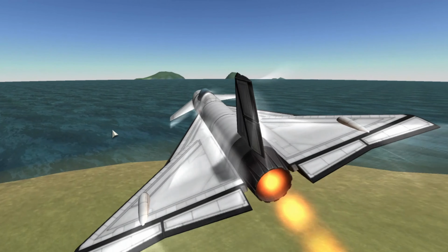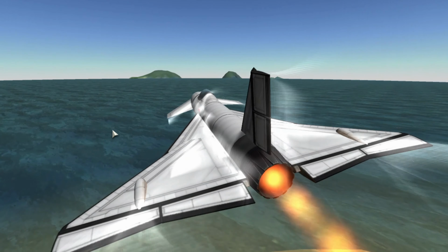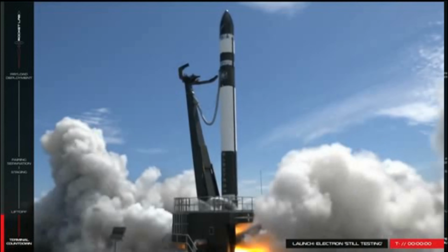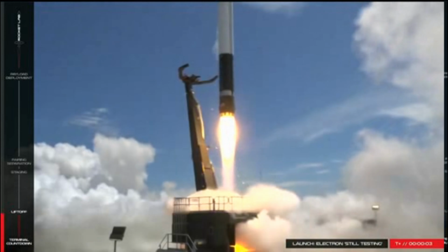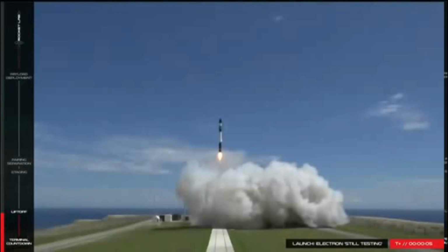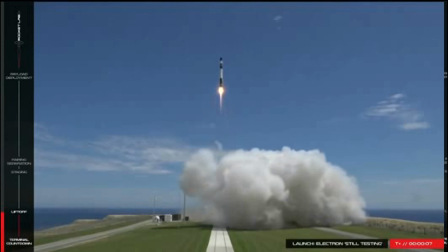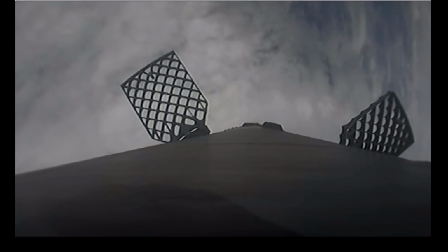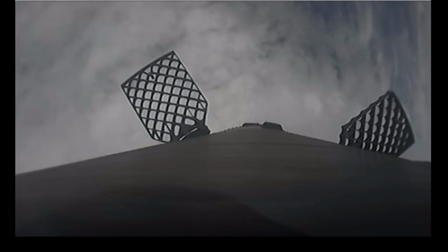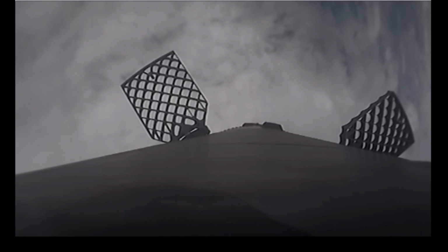Symmetrical airfoils are actually quite important in the aerospace industry. You might look at a rocket and think that there aren't any airfoils on it, but rockets are actually symmetrical airfoils. The Falcon 9 would be unable to land so precisely if it wasn't a symmetrical airfoil. The grid fins and cold gas thrusters on the top of the Falcon 9 booster will turn away from the airflow so that it starts producing lift that will move the booster's trajectory closer to the landing zone.